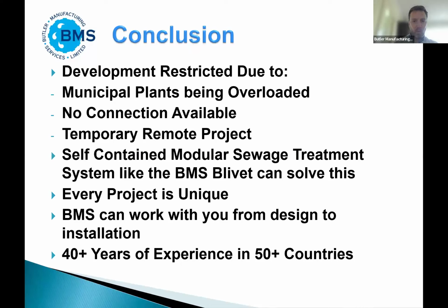So, in conclusion, there's a lot of developments which can't go ahead at the moment, especially housing, commercial and tourism, where the local municipal plant is overloaded, and typically it's organic rather than hydraulic overloading. So a temporary sewage treatment plant is a very viable and good value solution to allow a development to go ahead. Typically, most planning authorities will accept it. We can do the full design and planning for submission to planning, and they're working at multiple locations around Ireland and around the world, enabling housing and commercial developments to go ahead.